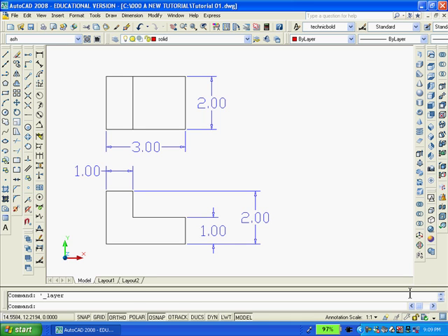Now I'm going to use AutoCAD's rectangle command and make two rectangles from the top view and move them to the right. It is the two red rectangles on the right which are going to be the basis for creating the solid.